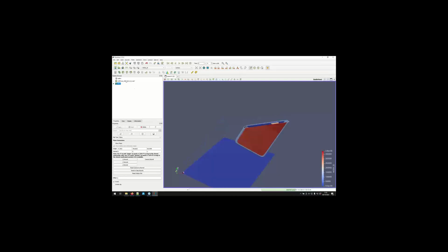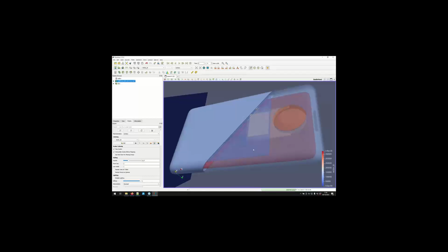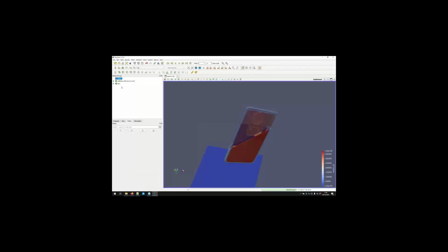What is very powerful in ParaView is that you can display anything from the pipeline in the same view. So for instance, let's also display the initial data and tweak the display a bit to add some transparency. With one filter and by playing with opacity, we can very easily see what is inside, and have the whole model in transparency in order to get the context. The pipeline is a hierarchical set of operations built on the upstream sources, and you can add them and stack them. For instance, on the output of the clip, I can add another clip if I want to.